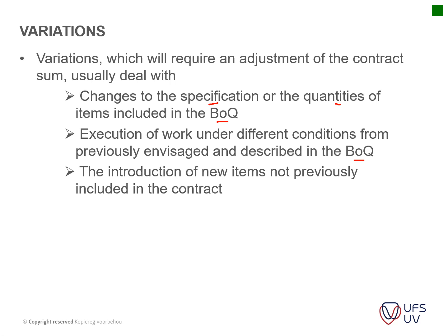Whereas if it's changed, for instance, from a non-compliant swimming pool at the start of the project to a FINA compliant swimming pool, where the tolerances are much stricter, it will constitute additional cost because the contractor has to spend more time in getting the accuracy correct. So I hope that explained it better for you. Or another thing might be getting the strength of the concrete, for instance, stronger also.